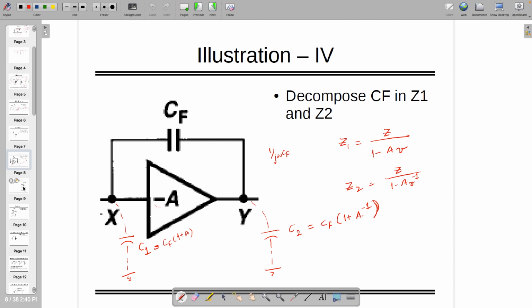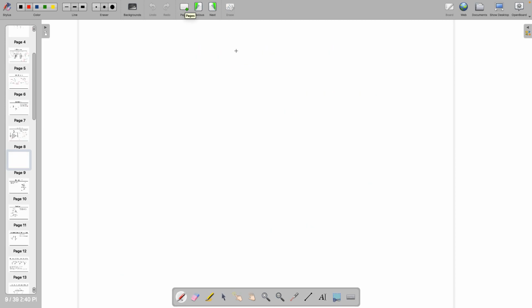This is similar to what you might have studied in feedback. I don't know whether I'll have time to teach feedback, but if I am not able to teach you, then go to my previous course, E203 analog circuit design, that's available on my YouTube, where there is one chapter on feedback with some proofs already given. If there is a voltage controlled voltage source kept in feedback, first of all, a voltage controlled voltage source has Rin of infinity and Rout of 0.